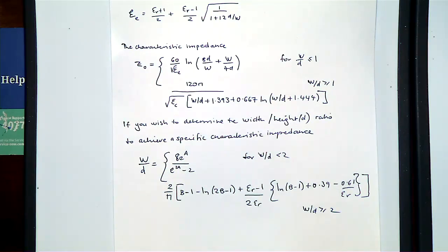Usually, if you're looking at FR4, for example, you have certain thicknesses of dielectric that you can choose from, right? You can't go there and say, I want 8.7321 millimetre thick layer of FR4, because the manufacturer is going to say, well, good for you, but these are the only ones that we sell or produce, right?